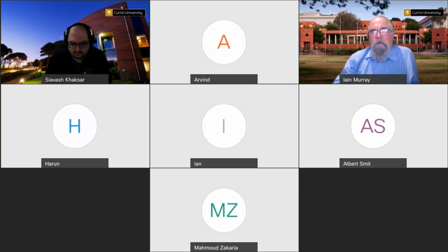My first way of looking at it is to do an FFT on it, look at the frequencies, find the frequency components of the click you're looking for, and threshold on the level of that frequency for those different clicks. Then maybe set up a fuzzy logic system, which requires very little processing power, to determine which category of click it belongs to. Fuzzy logic can be implemented just in a lookup table, so once you've worked out each of the decision areas, I've forgotten what they're called, it becomes very easy to implement in a very low power system.